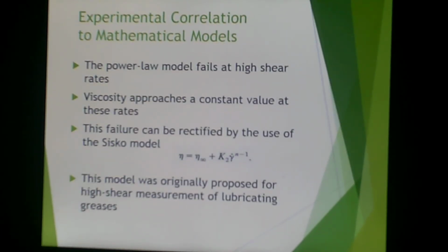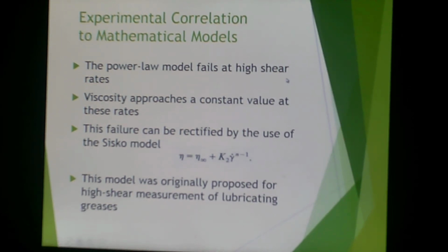One problem with the power law is that it fails at high shear rates. The viscosity approaches a constant value at these rates. But you can rectify this by using the Sisko model instead. So again, this equation here, it being the Sisko model. The Sisko model originally was proposed for high shear measurements of lubricating greases, which is why it's more appropriate at high shear rates, more appropriate than the power law.